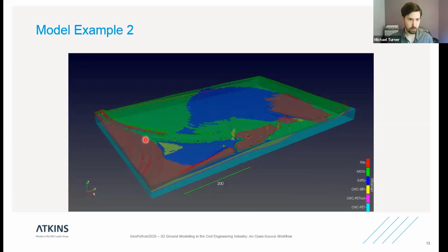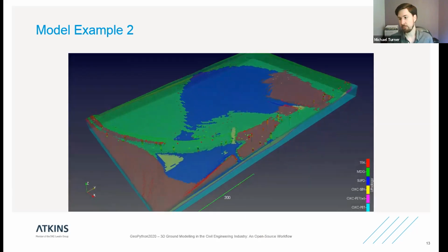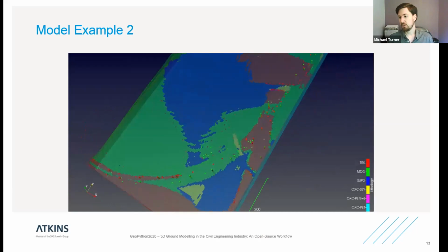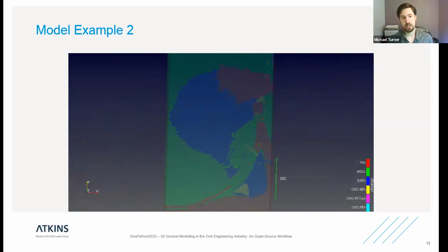There's actually a junction and another embankment coming down here and one down here. And the scheme we were working on was worried about this embankment curving through the middle. So what you end up with is all the investigation positions lined up along that embankment, and then no information on either side. And that's nearly always the case in any linear infrastructure scheme.